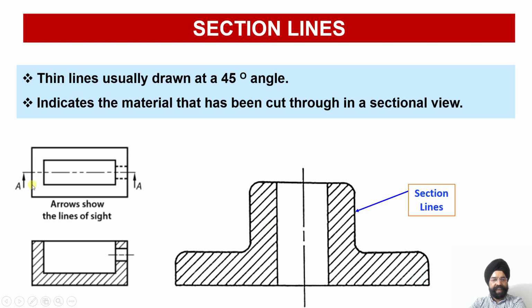You see, let us say we have this object. If we have this object, I want to look into the interior. If I draw the drawing of this object, two dotted lines will be available, which will show that there is some discontinuity or hole within this surface. I want to verify whether or not there is some hole. What will I be doing? I'll draw a chain line and then put down the arrows over there. I'm going to cut this in two halves. So 50%, 50% over here.